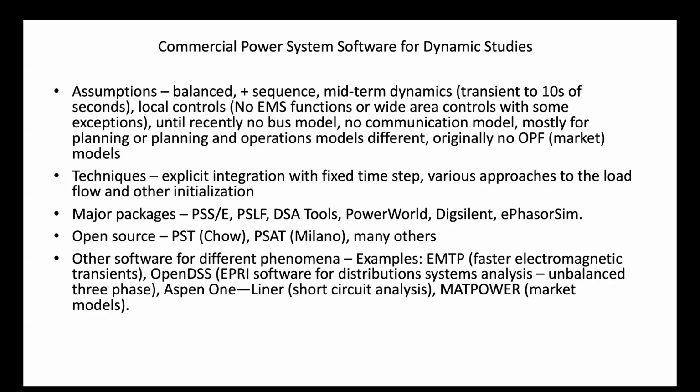It's sufficient for doing AGC and restoration, but without the numerical integration routines. It's a load flow with a frequency that can vary somewhat based on the balance. So it's pseudo dynamics: everything is done as snapshots of algebraic equations. Some people call it a governor load flow, because you allow different frequencies.